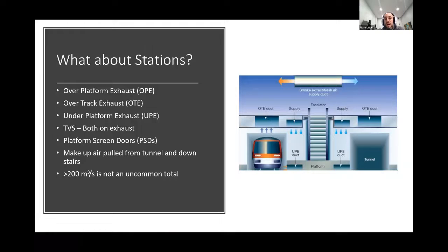So it's not uncommon for these to also have smoke baffles. And I think Jared Alston, who's designed a lot of tunnel systems, used the word architectural commitment, which is a good word to think of when you think of how stations should be designed. There will be a lot of architectural design particularly to assist in that fire mode, to keep a deeper smoke layer down by the platform and prevent it from coming up.